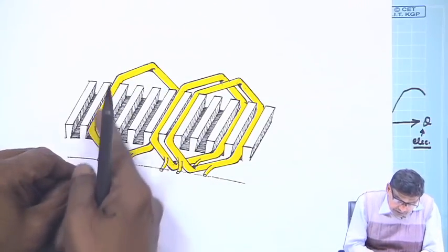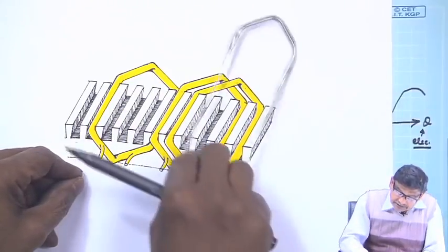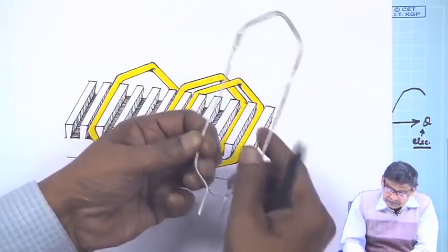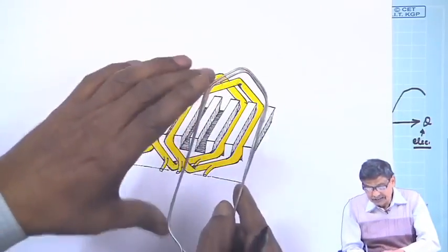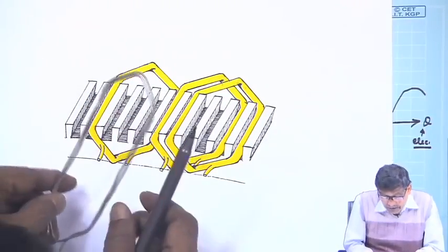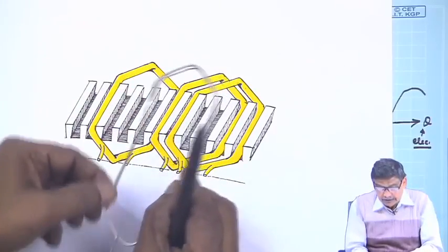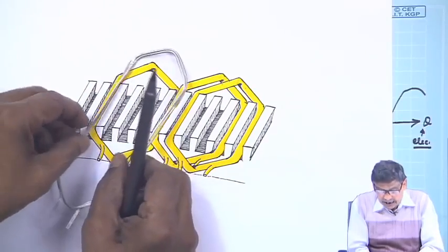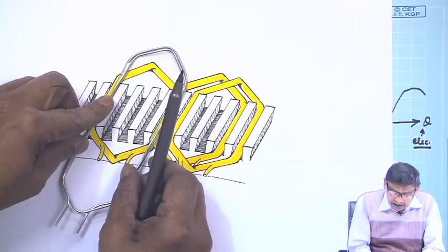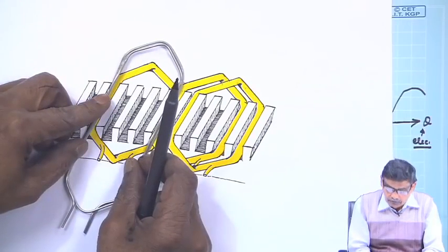You take a piece of wire, go around it several times like this. Here I have moved twice. So, the induced voltage in this conductor, all the EMFs will be added up, provided you have seen that if this is called one coil side, and one coil side at any time is under the center of the north pole, the other coil side will be under the center of the south pole.